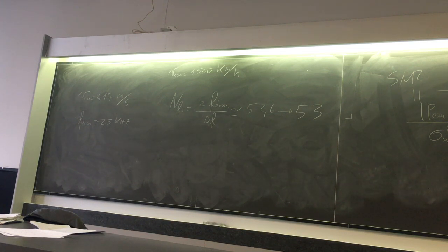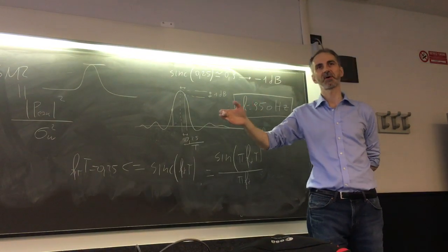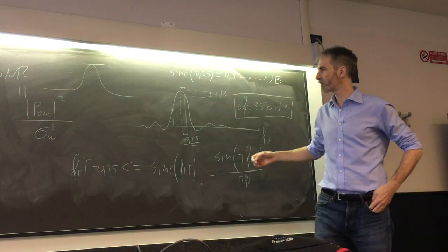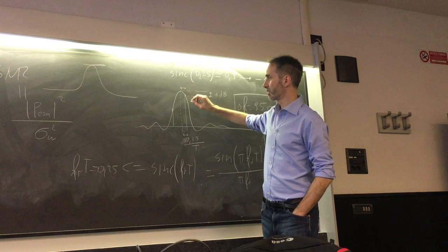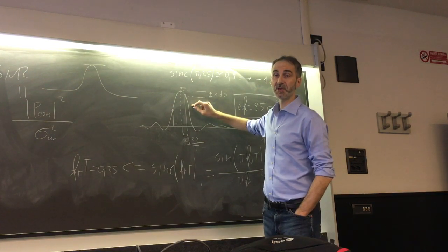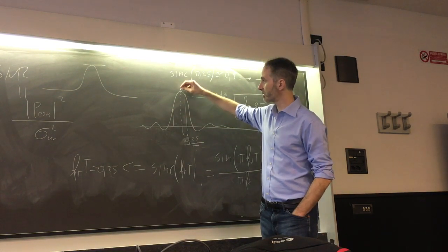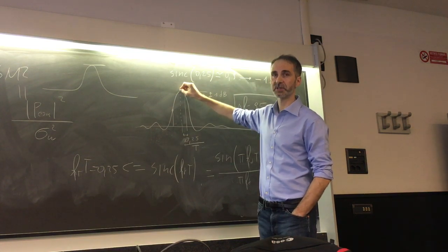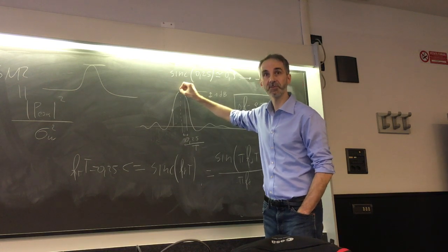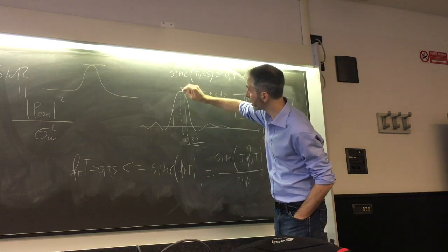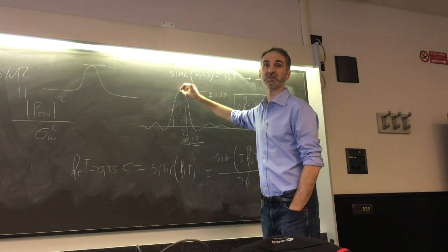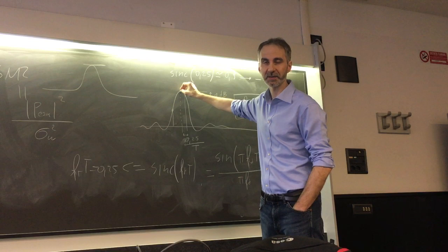If you compute this for an infinite number of frequencies, the best you can do, then you get a cardinal sine. If you sample this cardinal sine in the peak, then you get the same signal-to-noise ratio that you would get in the absence of Doppler frequency, because when you sample in the peak, it means that you have perfectly compensated for the velocity of this target.